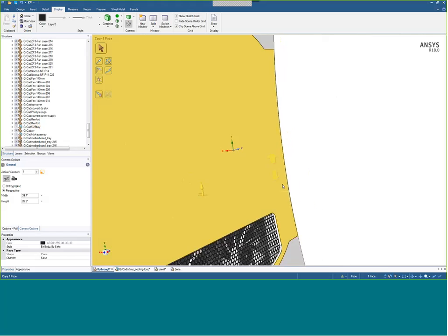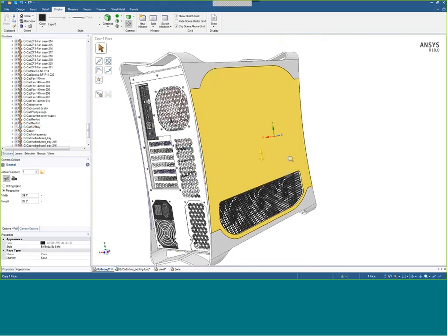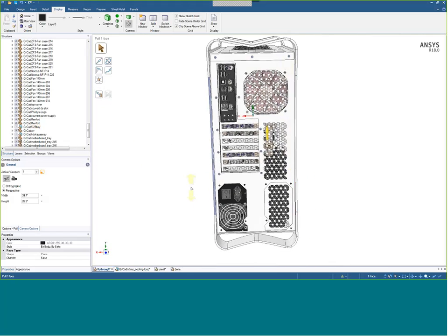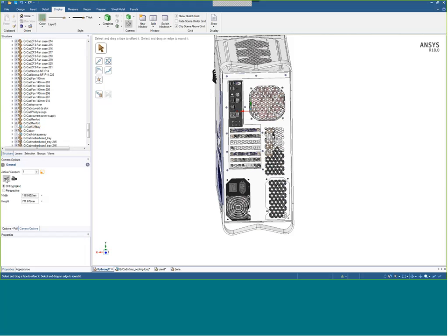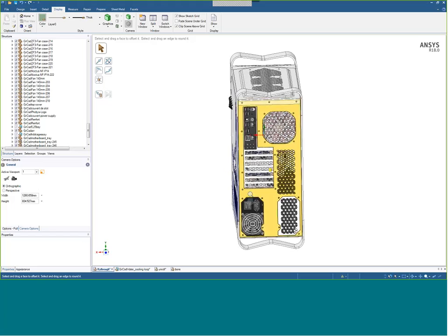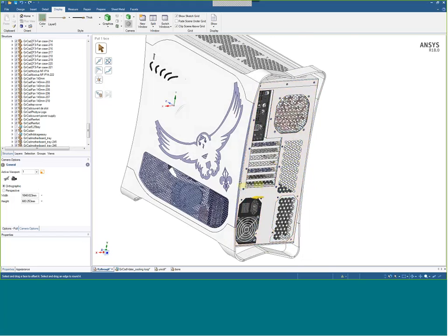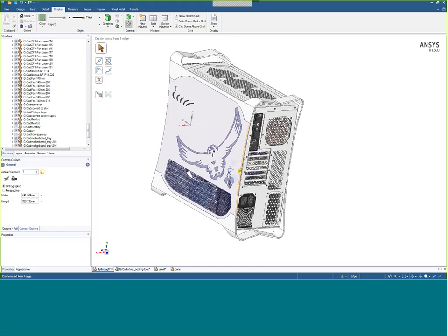And one other thing to point out, we get a lot of people who are doing fluid simulation, and they want to make sure they go inside and tag stuff, maybe name selections. Fly-through might be a really great tool if that's your workflow, trying to look inside of a volume and make sure that you label all the faces. And once you're done, just simply go back to orthographic and turn off fly-through, and now we're in our normal spin, pan, zooming mode. It's there.